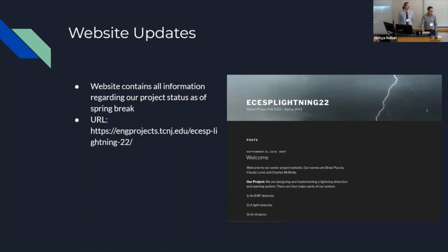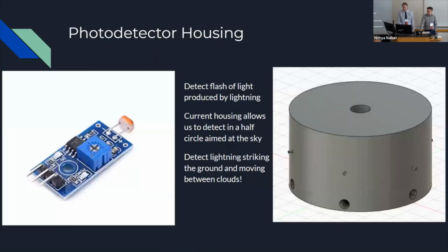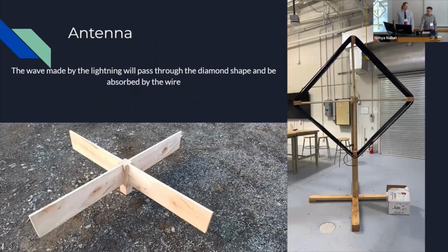Have you looked into some of the existing networks? Yes, there is one project that is kind of an open source project. I think it's German originally, and I think it's called Blitzortung. What they do is they have basically open source designs of systems for lightning detection. They use a lot more digital processing and more advanced circuit boards than us. So that was used to get the stages of the conditioning circuit underway and figure out the best way to design the antenna, which is how we ended up on the frame antenna here. And we decided to just stay with a passive loop because it's a bit easier of a design and requires a lot less understanding of the network. And so that's why it's a bit bigger than most things that come out. It's really just so it could resonate. It has a self resonance at 300 kilohertz.